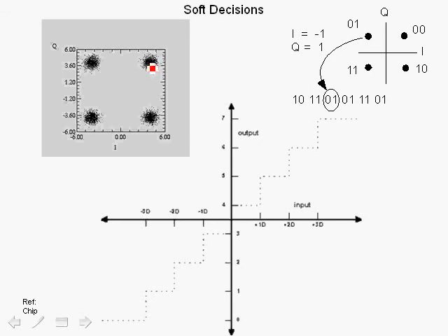So rather than use Hamming distances, we actually take the received vector as is, and we use the Euclidean distance. So we measure the distance directly in terms of the difference between the vector lengths. This, of course, would require floating point operations and a huge amount of complexity in order to compute all the metrics.